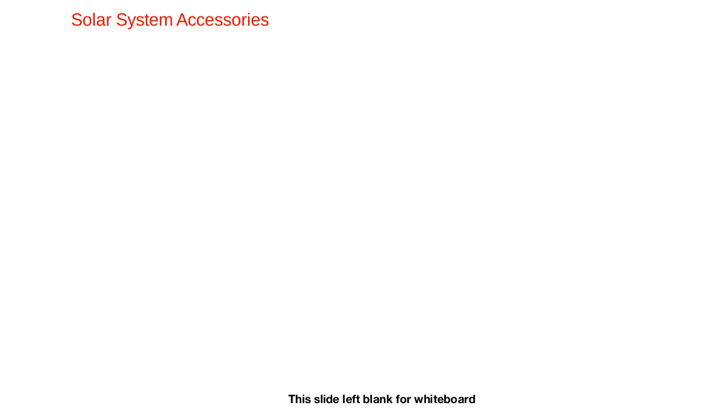And also we talked about the PV system layout. We say this is how your PV system is, a block diagram representing how components of the PV systems are interconnected. In that layout, we talked about the first component in the PV systems, the PV array. After the PV array, we have the charge controller, the DC load, the battery. From the battery, we have the inverter, and then the AC load.